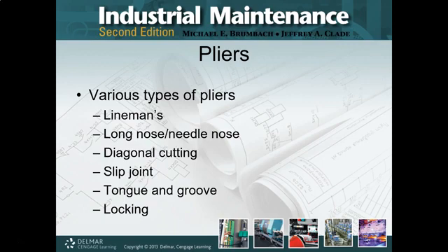Now we've got into the gripping stuff. We've got slip joints. They're not the greatest. They tend to literally slip, but you can adjust the size of them through a slip joint. Not my preferred, but if that's all I got to use, I'll use them. My preference, if I have to do an adjustable gripping one, tongue and groove is the way to go. I've got several examples of those. There's also locking.